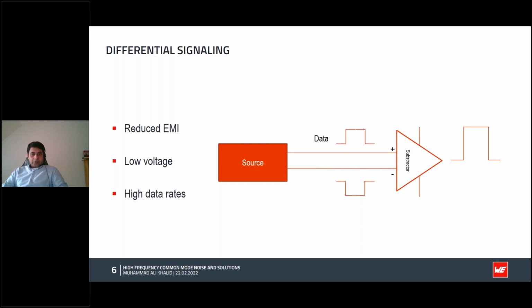The second point is about the differential signals. They also generate their own EMI while transmitting information. However, because the positive and negative signals in a differential circuit have opposite polarity and equal distance, this effectively cancels out any EMI emissions.